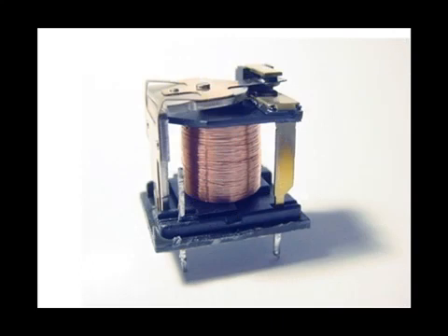Once the relay became known as a device, it was not long before engineers realized that there were other applications for contact relays. If you could use a relay to relay a contact closure into an isolated circuit in order to restore the voltage levels, then you could also use a relay to relay a contact closure into an entirely different circuit with an entirely different voltage type and level.